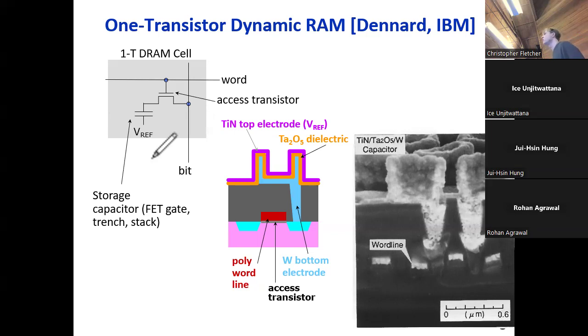So there's kind of two overhead operations here. There's the fact that this is a destructive read, and there's this refresh operation. That's kind of the way to think about DRAM. It's very dense at the expense of speed. We've gotten the ability to store a single bit down to a single capacitor and an NMOS. But what we're paying for that are these overhead operations that are not associated with the operation that we actually want to perform. Any questions on a DRAM cell?